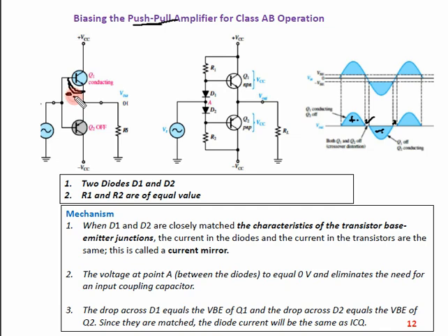So there will be no IB, or base current, at the base until the signal goes greater than 0.7. So it's just a question of providing a biasing of 0.7 over here, and similarly 0.7 in this region.